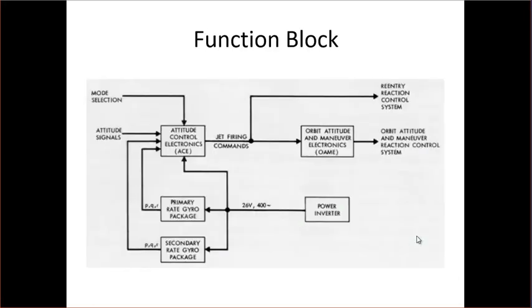So function blocks, this is what function block programming looks like. It's another graphical way to program, and like I said, typically you'll see function blocks used more in distributed control systems. Like at the power plant, the main control system that's controlling the power plant would be called a DCS, a distributed control system, and it would typically be programmed using function block programming.